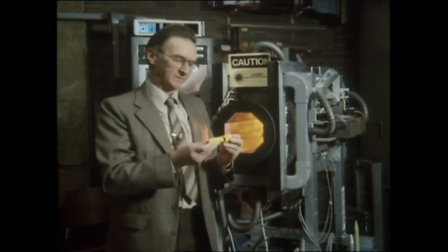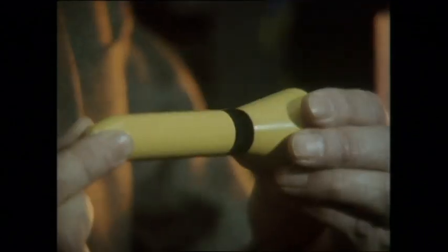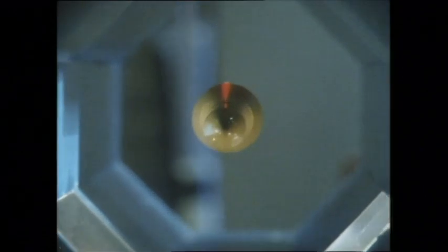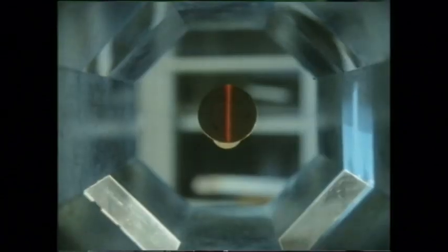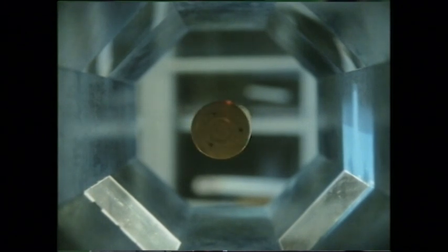Now, we don't just have one single movement to control, the up-down. We've got to control fore and aft, left-right, as well as the 3 rotations. Once the computer has complete control, the strength of each of the electromagnets can be varied to put the model through a series of pre-planned moves. As the wind tries to move the model, the computer adjusts the currents in the magnets to keep the model in place. The extra current needed is a measure of the wind's effect.